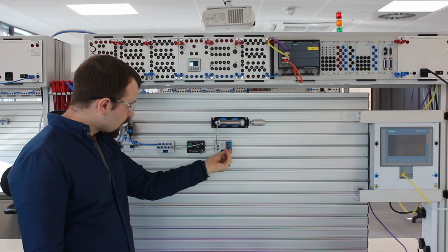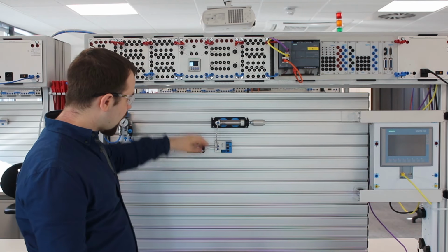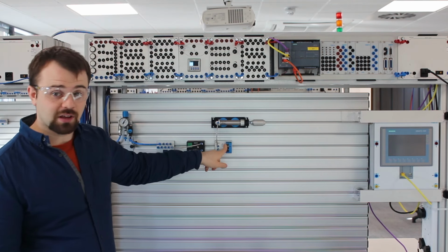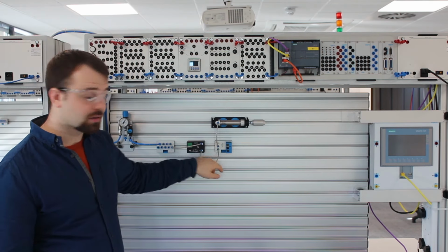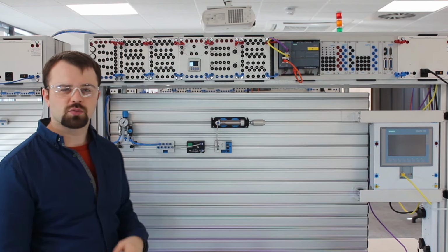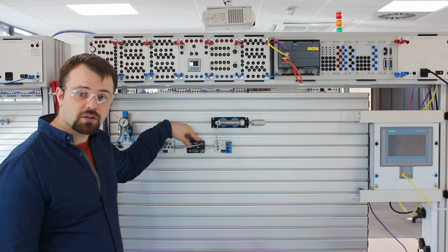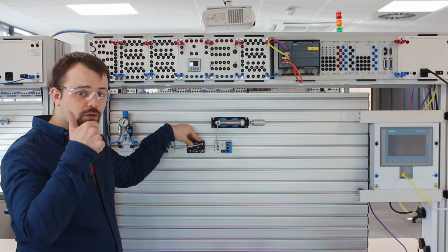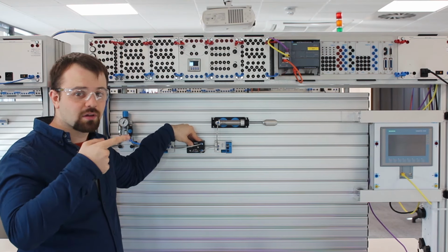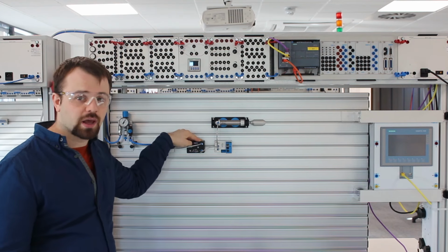It has a little dial that allows us to adjust the amount of time that it's set for, and what it does is as air is put into port 1, it starts to count down time until it gets to the end of the timer, and when it gets to the end of the timer, port 2 is opened and the air goes into the cylinder. So it just works like a bit of a delay. So if I turn on the air to the system, press the button, 1, 2, 3, 4, 5, cylinder goes out. If I let go, the valve immediately resets and we can do it again.